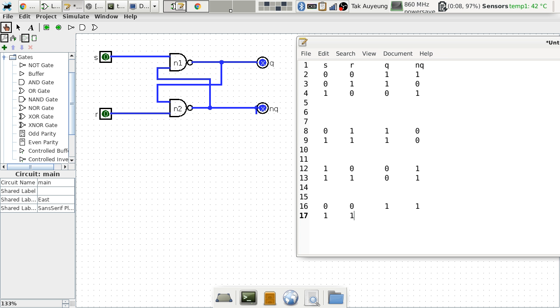It's not going to be a very long time. It's going to be measured in nanoseconds, probably a fraction of a nanosecond these days. But there is definitely a certain length of time where the inputs of N1 and N2 will both be 1s. And after that amount of time, which is the propagational delay of a gate, both gates will now switch their outputs to 0s. So we now have 0 and 0 here.